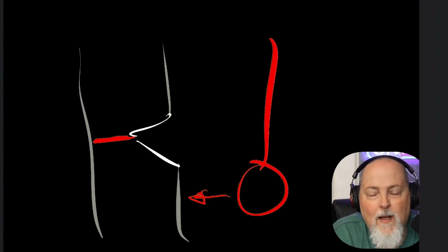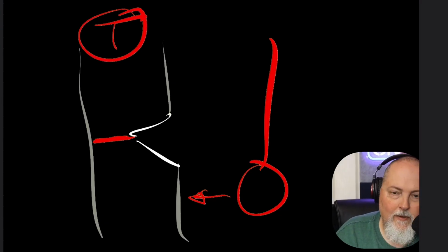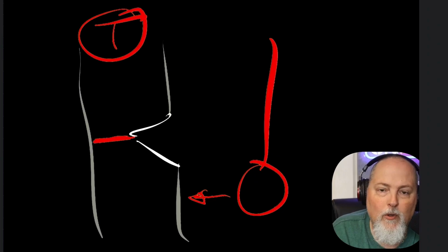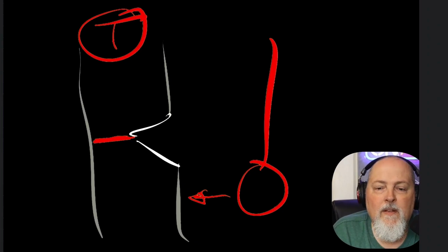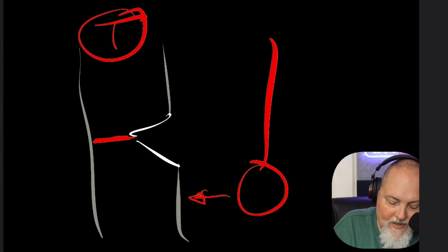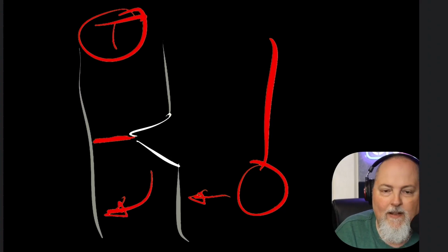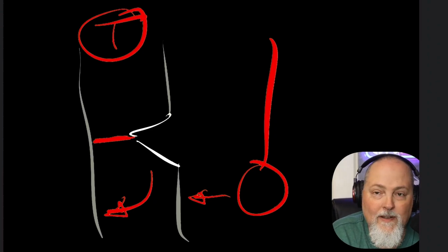The test is commonly used to evaluate ductile to brittle transition behavior as temperature decreases. So they'll change the temperature of the material in the environment as they do this. They'll have it in a warm environment, and they'll cool it and cool it and cool it, and they'll strike it and strike it. And so that evaluates that ductile to brittle transition behavior. And they're looking for, do we have plastic deformation? Is this just bending down and no crack? Is there a crack that happens? At what point does the crack happen? Because eventually that crack's going to happen.